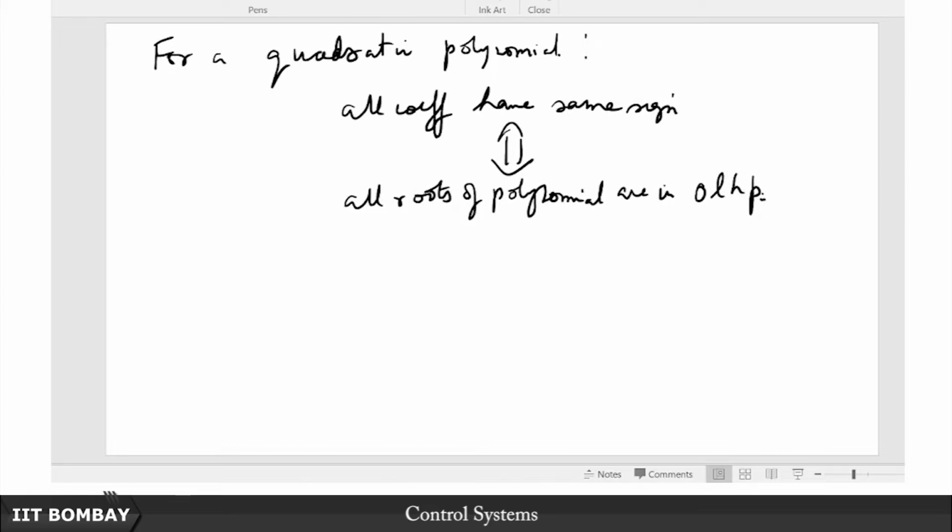So the strategy is, we do not want to actually check for interlacing, because again remember at any stage, to check for interlacing you have to evaluate roots, which we want to avoid at all costs. So now that we have this degree reducing algorithm that we have shown you, we will reduce it until we reach this quadratic stage, and then at this quadratic stage we check if all the signs of the coefficients are the same.